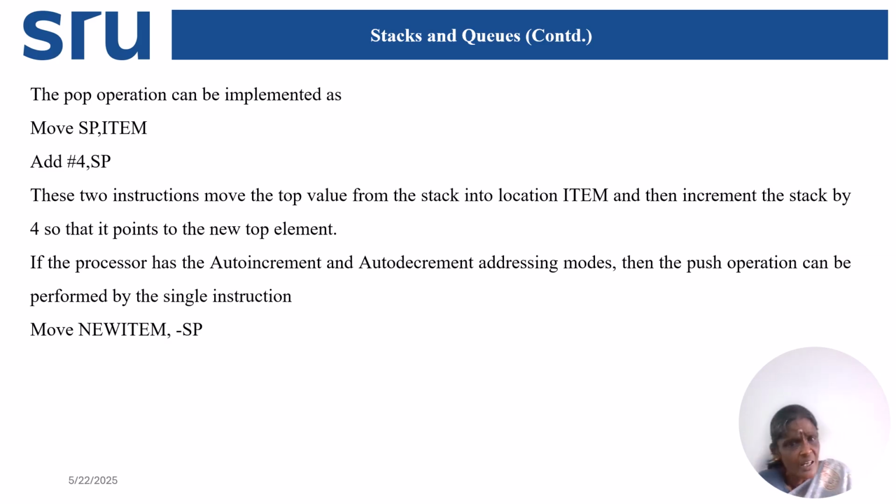If the processor has auto-increment and auto-decrement addressing modes, then push can be performed by a single instruction, move new item. So the push operation means minus SP. The pop operation means plus SP, no need to put a plus in prefix. But in the push operation we need to put minus because it is decremented. So that is why minus SP.